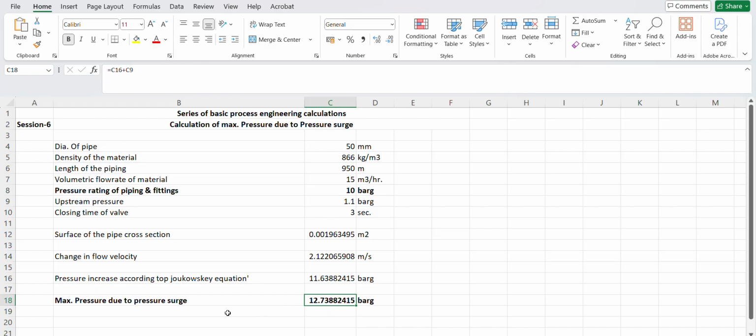So the pressure surge is proportional to the flow rate as well as the piping length. I'll put it down to 10 meter cube so it comes to the original calculated pressure. Then as we increase the length, the surge pressure goes on the upper side.